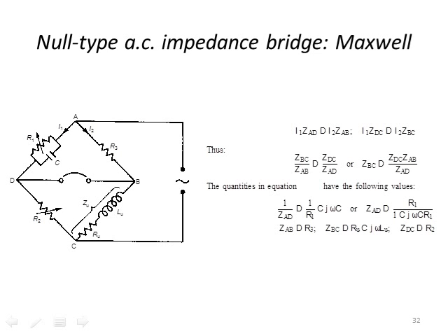So capacitors are more easily accessible than inductors, and then you have a variable resistor here, so you can read out an inductance using a capacitive type of bridge structure, which is quite useful.